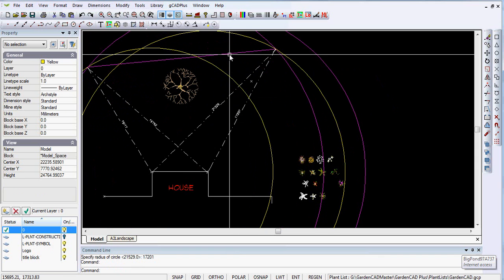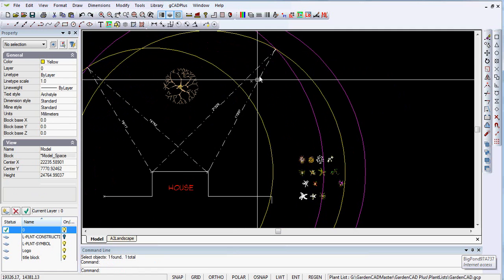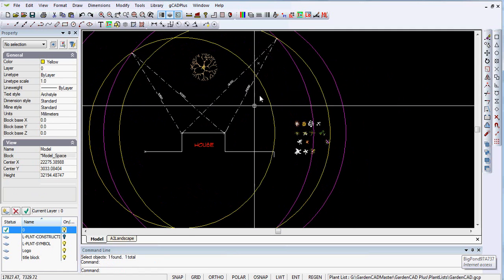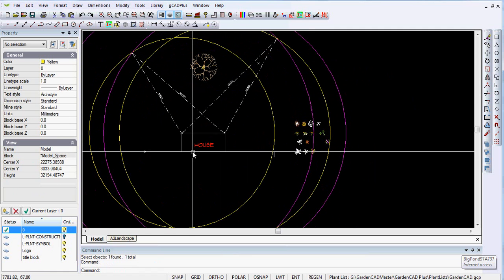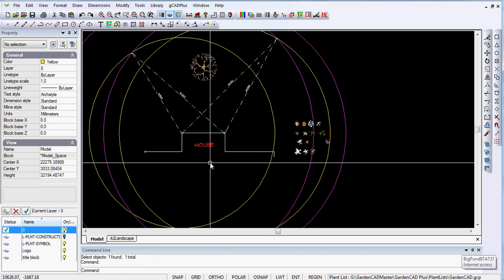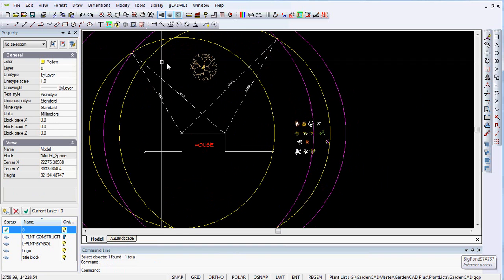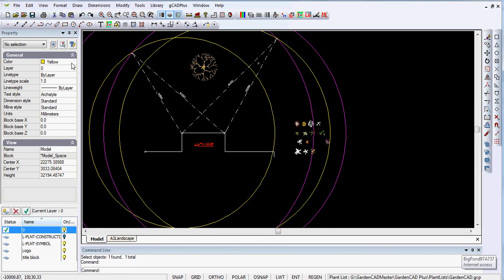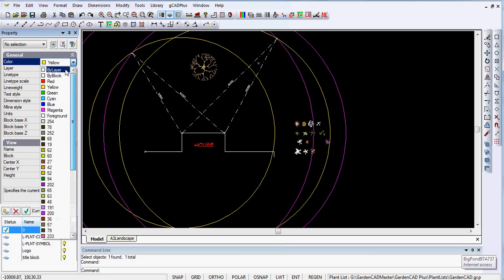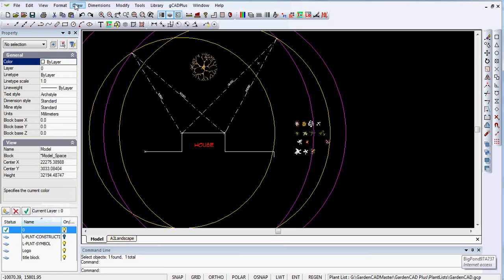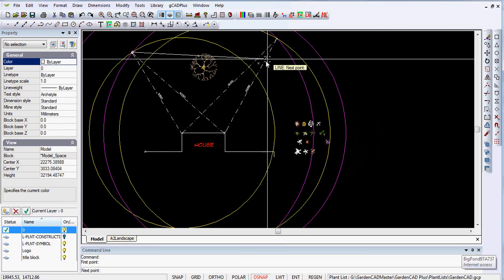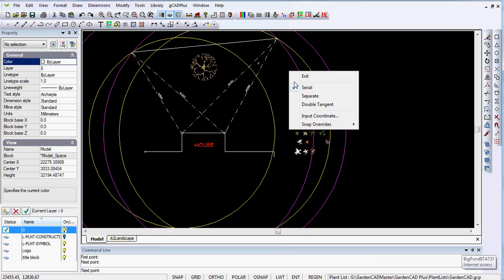Let me now eliminate that back boundary because you wouldn't have it. You've been on site, jotted down these measurements, come back to your CAD station, put the circles in as we've done. Now to pick that back boundary, we're just drawing by layer, so draw a line from the intersection of those two circles to the intersection of these two circles, and we're done.